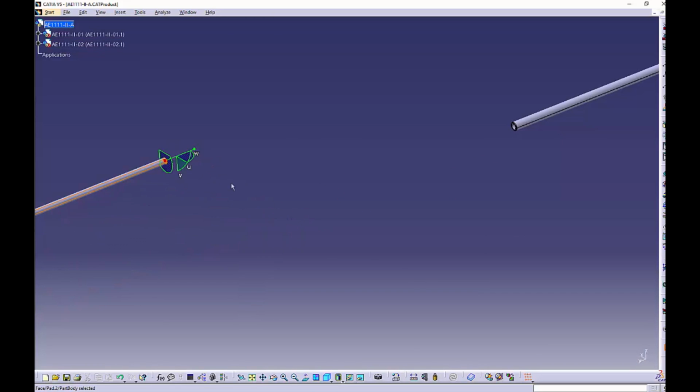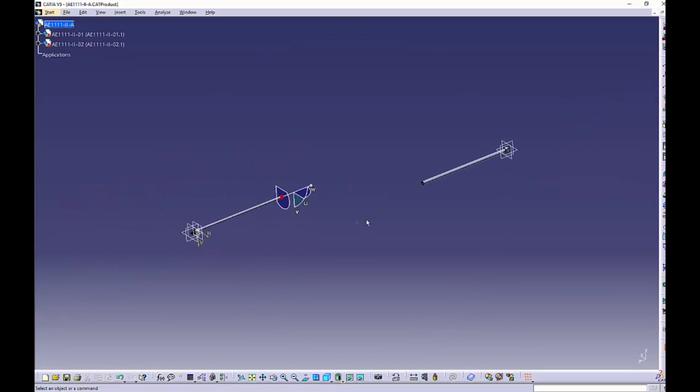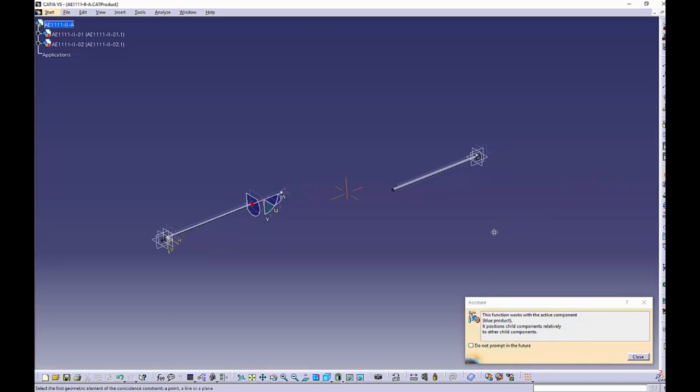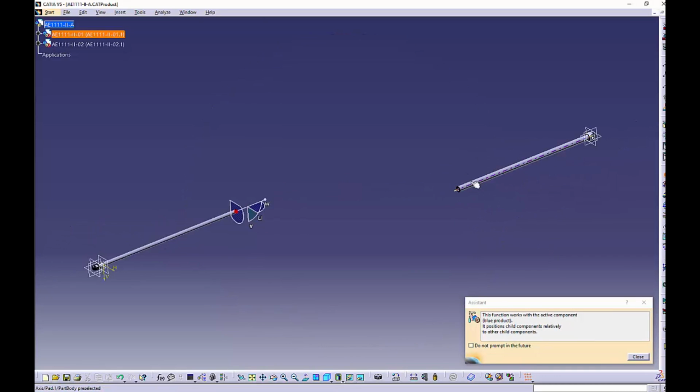Now we also have another problem. I showed to you like this. So now it is not constrained with this object, right? So there's a lot of distance. I want to make them constant. So we are using constraints like in the sketching part, but this time we don't make it iso-constrained, but also somehow iso-constrained. We want to constrain so we can't move it, so it has its fixed place. So we use from the right toolbar the constraint tools, and this one is called Coincidence Constraint. So select it, and now we can make constraints between 2 holes or stuff like that, or 2 axes, so they are on one line.